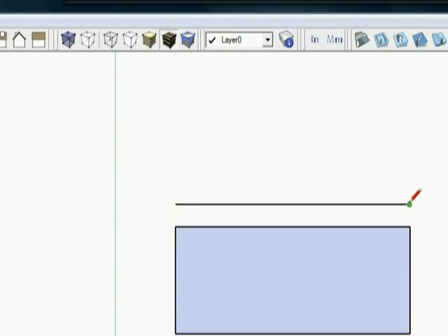So I can click, and then maybe I want to draw a bigger one, so I'm going to go up, and now that line is green. And you may say, well, why is that line green? Well, that is in reference to the y-axis here. So it's going to be green. And I can click, and I'll come out, and I can come down here to that line segment, hold it for a little bit, and then come up, click, and then come down, click.